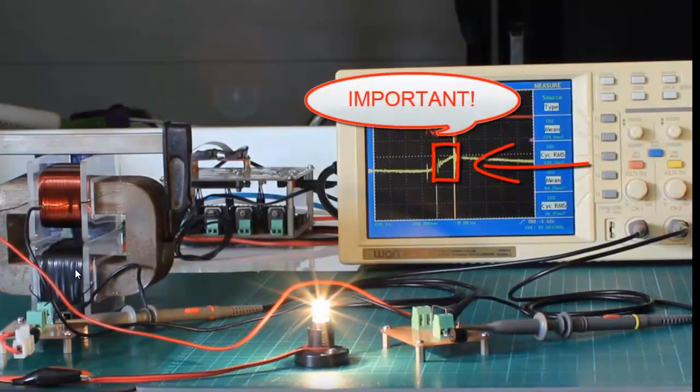If we had an input coil that had, say, 10,000 turns on it, with maybe 0.5 millimeter wire, or like I say 1,000 turns or something, then the response time on that coil is going to be very, very slow. It's going to take a fair bit of time to get that coil up to a maximum current, which we've already talked about in one of the previous videos, perhaps video 5 maybe.